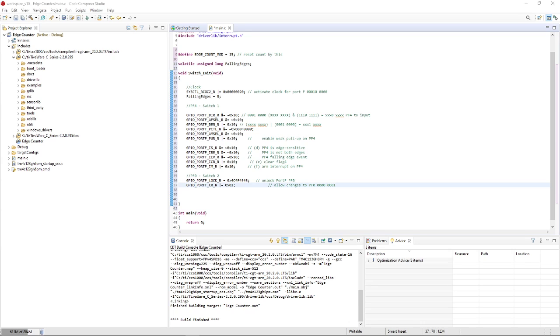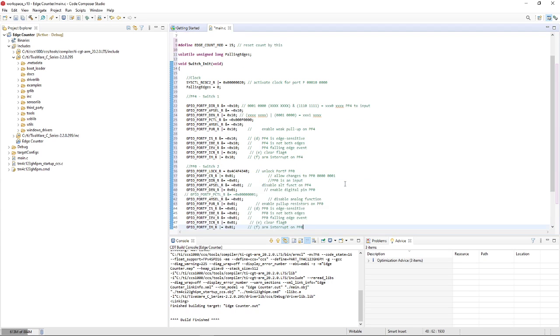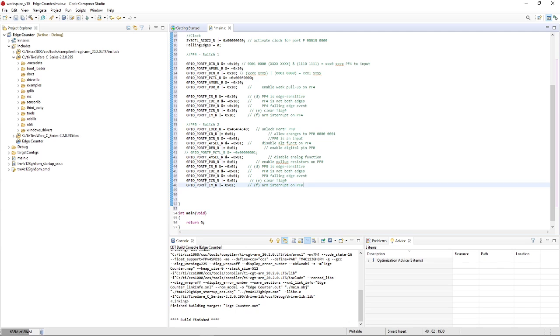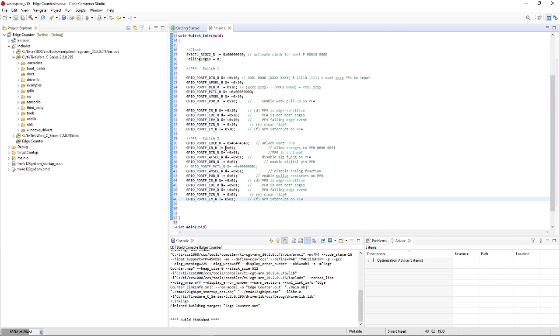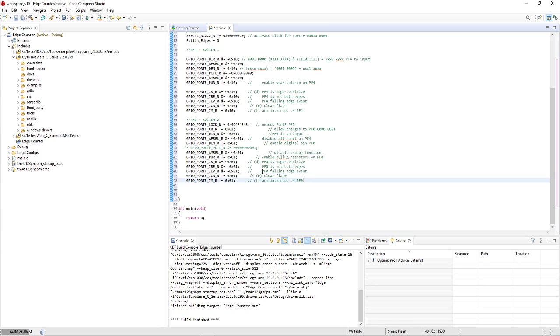And then everything else looks almost exactly the same, except you use the number 0 bit instead of the number 4 bit. So all of these registers do the exact same thing as they did up here. You just target a different bit, to tell the board to turn on those pins on the board. And then we have to do this.